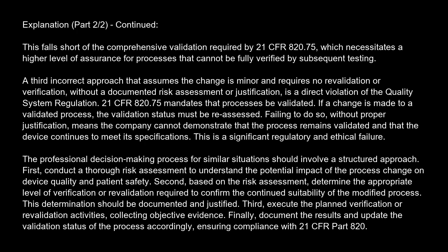The professional decision-making process for similar situations should involve a structured approach. First, conduct a thorough risk assessment to understand the potential impact of the process change on device quality and patient safety. Second, based on the risk assessment, determine the appropriate level of verification or revalidation required to confirm the continued suitability of the modified process. This determination should be documented and justified. Third, execute the planned verification or revalidation activities, collecting objective evidence. Finally, document the results and update the validation status of the process accordingly, ensuring compliance with 21 CFR Part 820.